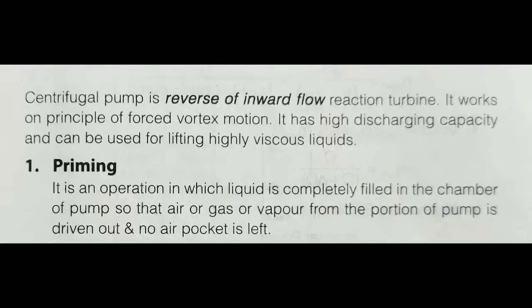Next is priming. It is an operation in which liquid is completely filled in the chamber of the pump so that the air, gas or vapor from the portion of the pump is driven out and no air pocket is left. This term is very familiar.